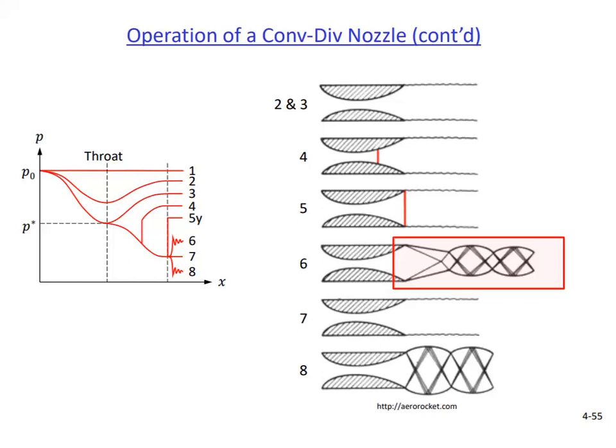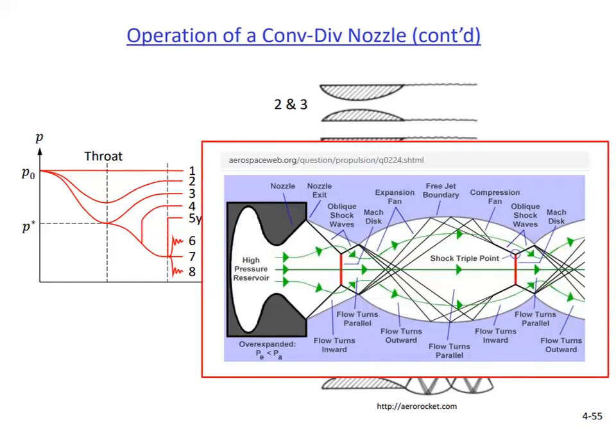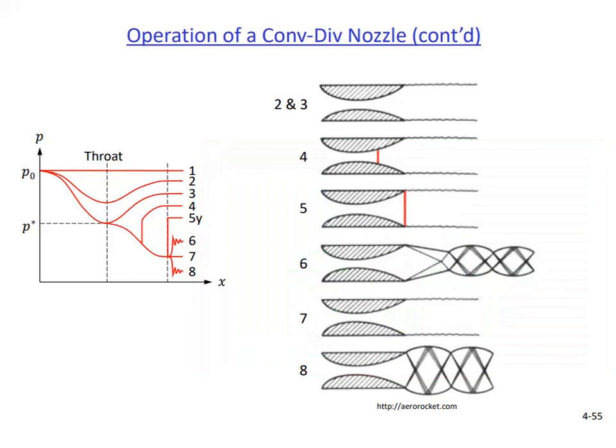The exiting jet is first squeezed by oblique shocks and then goes through a complicated process, details of which is shown in this figure. The jet goes through a series of compressions and expansions until it finds an equilibrium with the surrounding fluid. If you want to read the details of this process and study this figure in detail, its link is given in the previous slide.